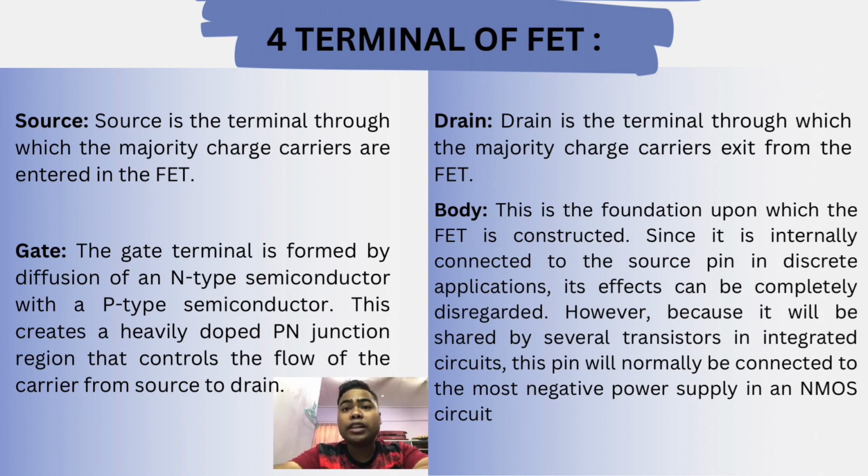The last one is body. This is the foundation upon which the FET is constructed. Since it is internally connected to the source in discrete applications, its effect can be completely disregarded. However, because it will be shared by several transistors in an integrated circuit, this body will normally be connected to the most negative power supply in an NMOS circuit.